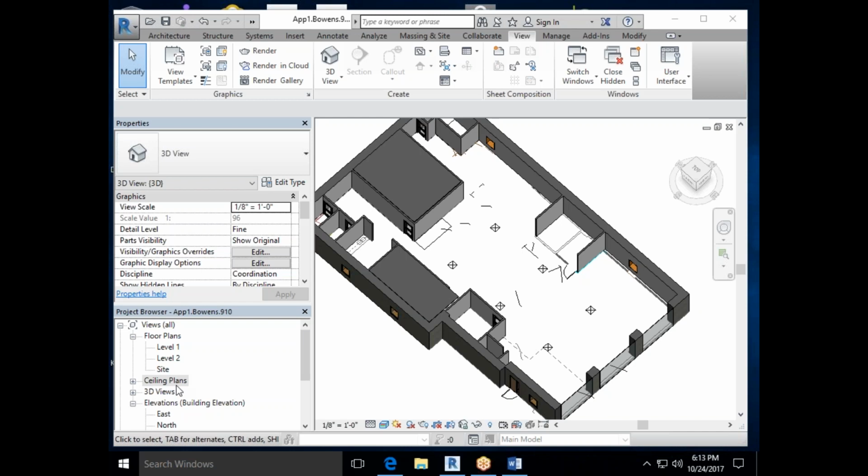But notice how it matters because, I think it was Katie was just talking, we can control the height on here to only show it so then we get rid of our doors so we're showing the right cut plan of what a ceiling plan would look like. But it doesn't really matter because they're just little pieces of paper. That's what I want you to feel the freedom of. We can delete them, add them. If we mess something up this week, we can move it. We'd even copy it from a level 2 floor plan onto a ceiling plan and paste it, and it would still work out. All right, so floors are similar.